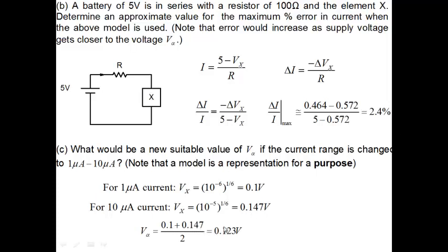So range is important. In the same way, we often forget when we take a diode and approximate it by 0.7 volt that this approximation is valid over a certain range. If I go to a different current range, the diode has to be approximated by a different value of voltage. So these are all approximations, and the approximations would depend on what range of current you choose here.